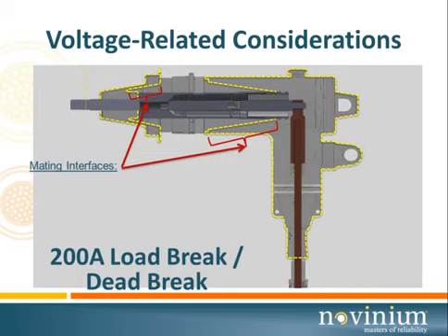Now, the more critical area for greasing is in these two interfaces. And by far the worst area is this, the operating interface. But for the minute, let's just look at the two of these together. We want to make sure that we use the proper grease. Now, the materials that are used to make almost all these separable connectors is EPDM. It's an oil-based rubber.